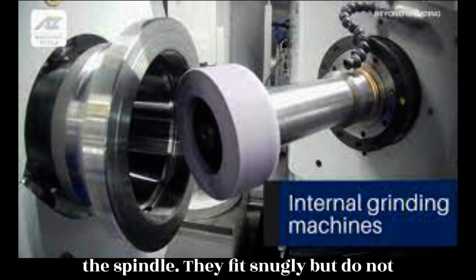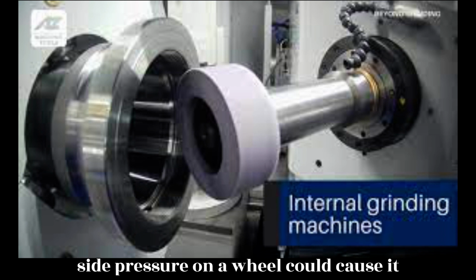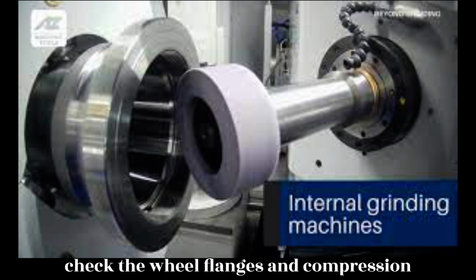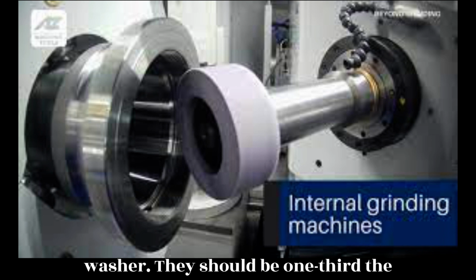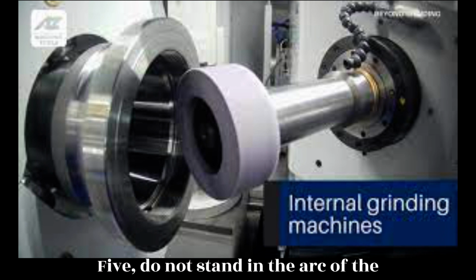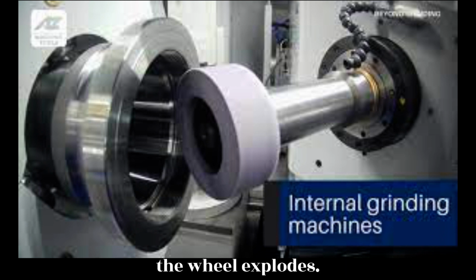They fit snugly but do not require force to install them. Placing side pressure on a wheel could cause it to explode. 4. Check the wheel flanges and compression washer. They should be 1/3 the diameter of the wheel. 5. Do not stand in the arc of the grinding wheel while operating in case the wheel explodes.